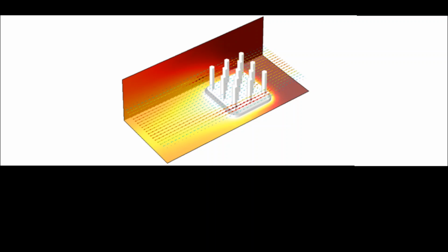So these heat sinks can be used to increase the surface area of certain electronic components that need to be cooled down. And by increasing the surface area, we increase, let's say, the effectiveness of the cooling process. So if this can be smartly engineered to occur within a compact volume, the cooling device will also be obviously more efficient. So in this case, we can observe that the thermal energy is transported through diffusion in the aluminum heat sink material, and then obviously through convection into the cooling air.